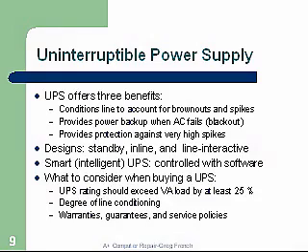What to consider when buying a UPS. The UPS rating should exceed the VA load by at least 25%. Also consider the degree of line conditioning, warranties, guarantees, and service policies.